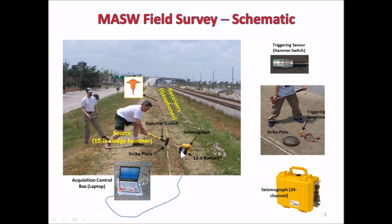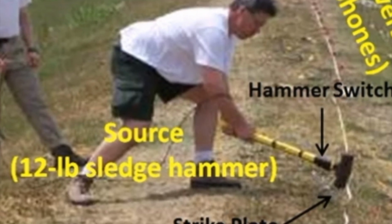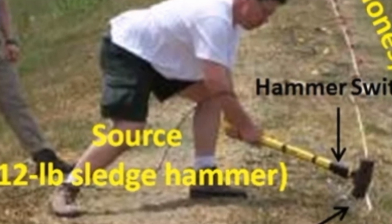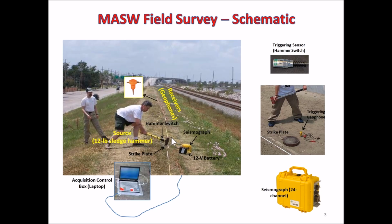And then when you make an impact by using a typical seismic source like a sledgehammer, which has this kind of hammer switch attached on the handle, the hammer switch detects the impact and sends a signal into this seismograph to start recording. So as the generated seismic waves, which are propagating into all directions, are passing through this geophone array, their vibrations are picked up by each geophone.